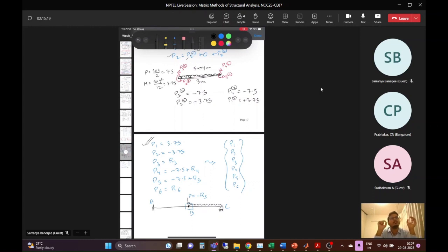The reason we cannot solve the problem is that we are using the stiffness method to solve the beam node by node. When we go node by node and only take the effect of the external factors on the nodes, and not the effect of the loads distributed over or applied on the beam as fixed end and equivalent loads, our problem does not have enough information to give us the answer.